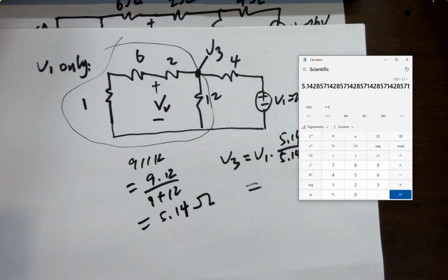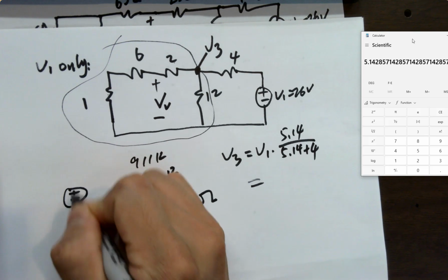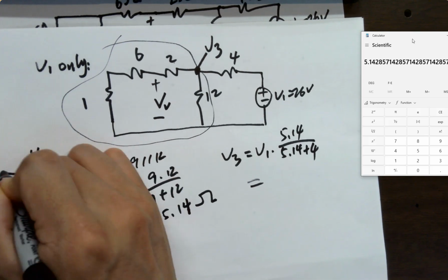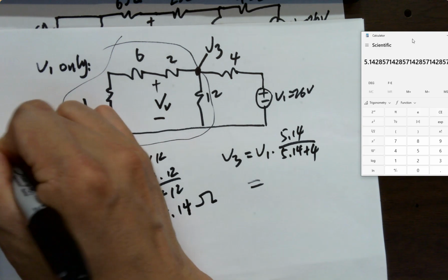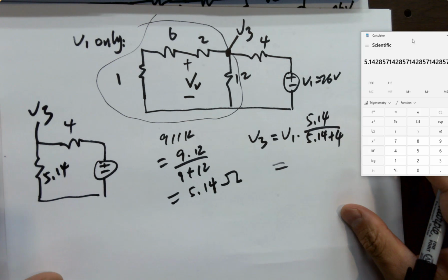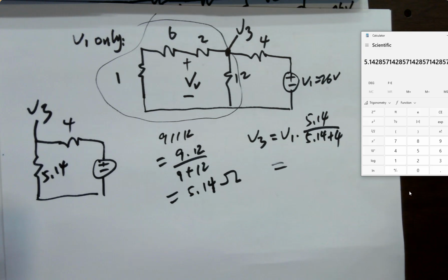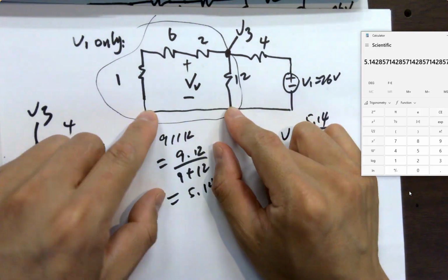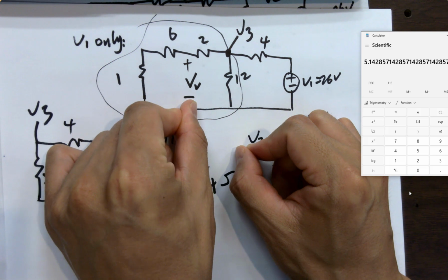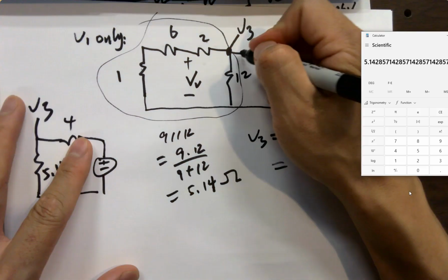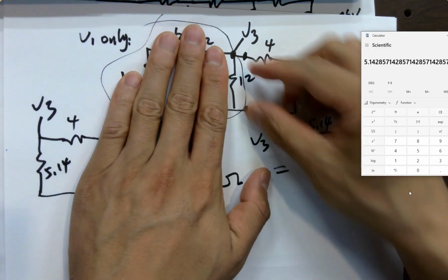Could you draw what that looks like with the V3? Oh, yeah. Right, here's V3. Oh, I know why. So it's still confusing you. You got a long wire here. It just melted, melted becomes one node, right? It's just one node. So if you just look at these two terminals, the whole thing here can be replaced by one resistor, just these two terminals.